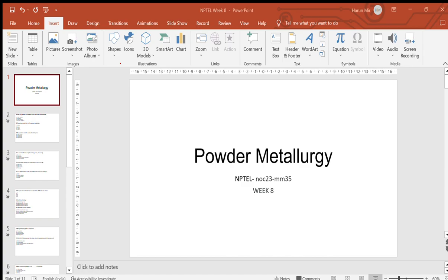You can, I think, answer. Fine and spongy. Right. The fine particles will have a high spring back because there are very small distances by which the dislocations can move through the material. So there are chances of release of the stresses at a much higher speed. Similarly, for the spongy particles, we can have a higher spring back during the ejection process.